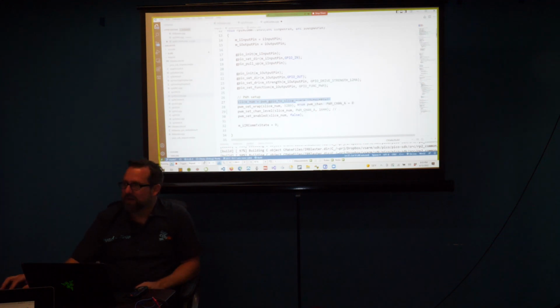Because if you look at the data sheet on the RP2040 and the SDK, these functions are very thin wrappers that go right to the control registers. If you look at the internal structure, there are 8 of these PWM engines, and that's why they call it a slice.